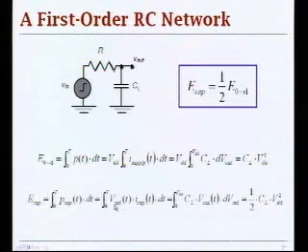The power is, as we defined it, the product of the output voltage and the current that goes through this capacitor. Then you have the current relationship C dV over dt, and dt cancels out, so you have C times V out times dV out, where the voltage at the output goes from 0 to VDD. When you integrate, you get half of this total energy.